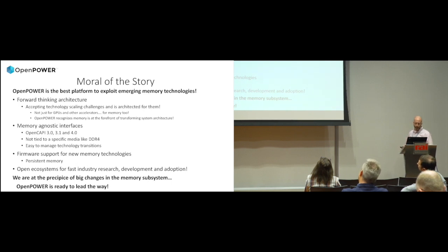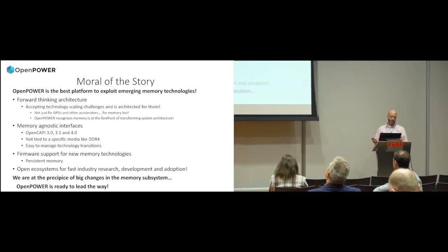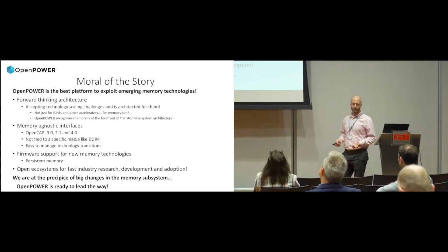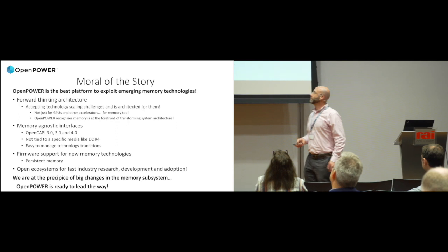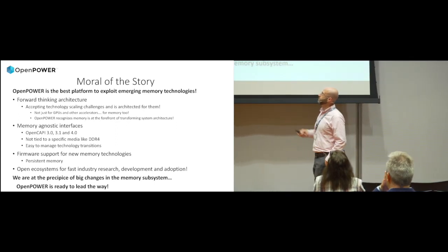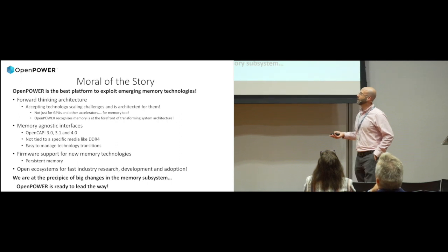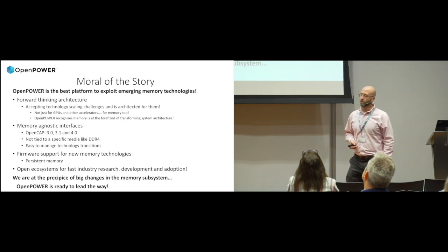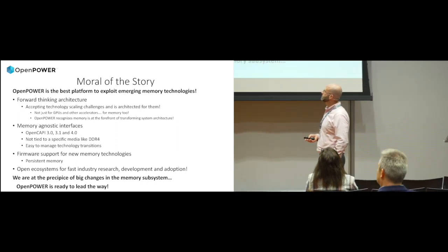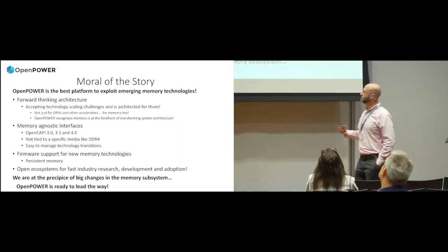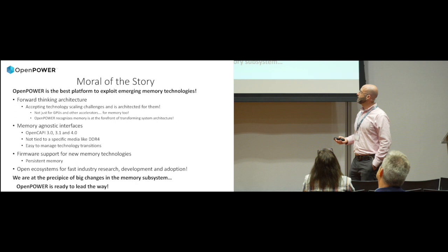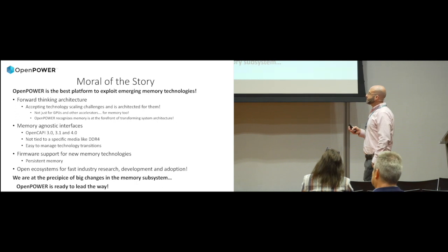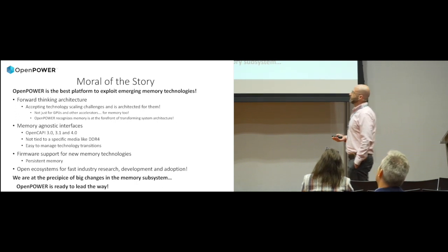OpenPOWER recognizes that memory is at the forefront of transforming system architecture. Namely, we're looking at memory agnostic interfaces so we can attach all types of different memories: the OpenCAPI 3.0, the 3.1, and the upcoming 4.0. We're no longer going to be tied to a specific media like DDR4. That makes it much easier to manage your technology transitions from DDR4 to DDR5, and emerging memory technologies. We've learned a lot of that in the past with our other buffered memory solutions, transitioning from DDR3 to DDR4.